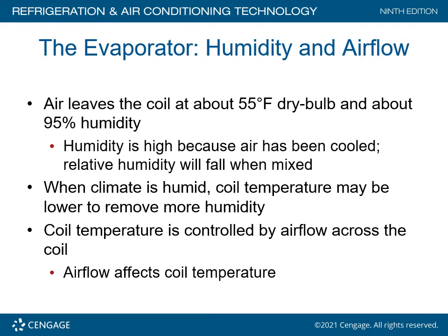A caution note. If you have too much air across the evaporator coil, what happens to your ability to take and remove humidity? Okay, so basically the coil temperatures will have to be lower in order to remove more humidity. But if you have too much air blowing across it, you're going to upset the balance where you're not going to be comfortable. Okay, too much air across the evaporator coil is just as bad as too little air.